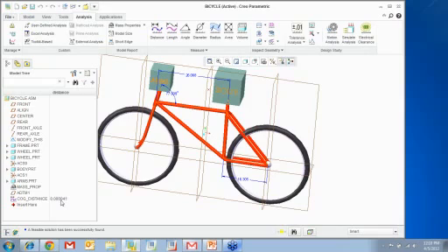All right. So this is behavioral modeling. You want to design your model such that it behaves in a certain way. Now, another use case for this is, say, for example, we are designing a crankshaft, and we want the center of gravity of the crankshaft to be right on the rotation axis.